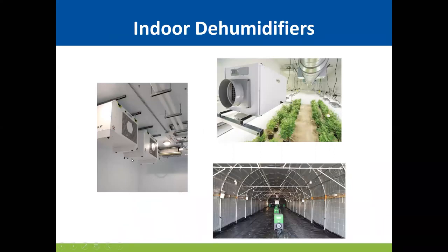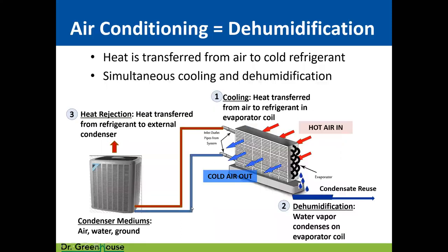We can hang them from the rafters, and they can be large or small. We also have these little roll-in dehumidifiers that we can use in a pinch or temporarily, and we don't need a permanent installation. Most of these are compressor based, but there are some desiccant based systems. Based on our analysis, desiccant probably only pencils out when you need a really cold and dry condition. But most of these compressor systems are relatively efficient, down to about 65 degrees. I'm going to get to that also in a minute.